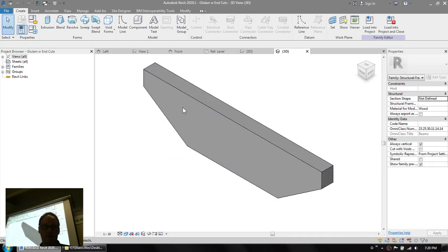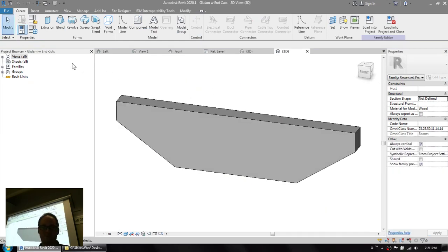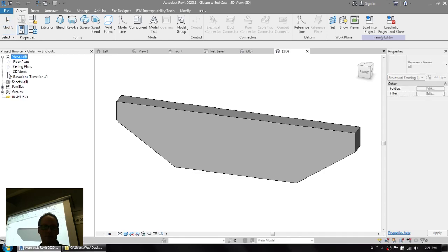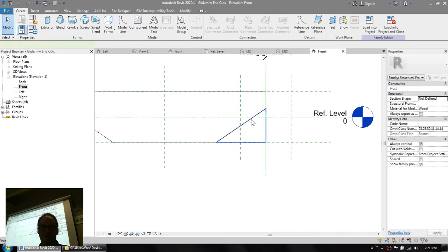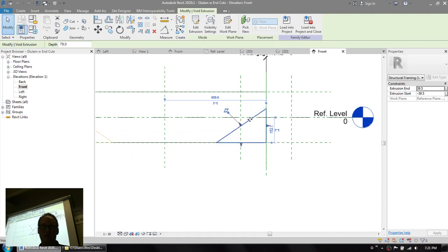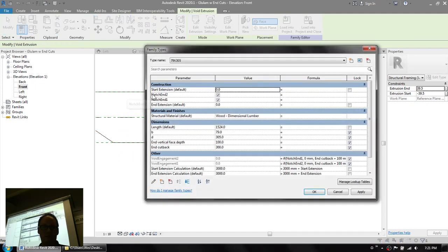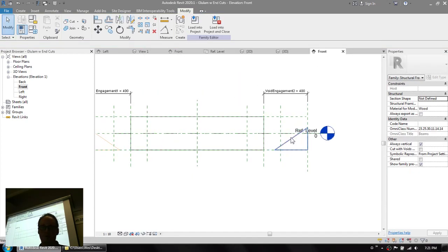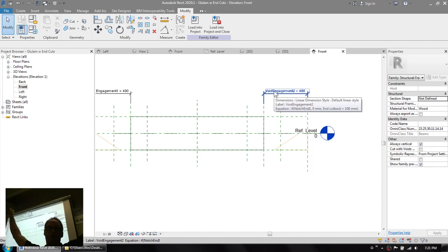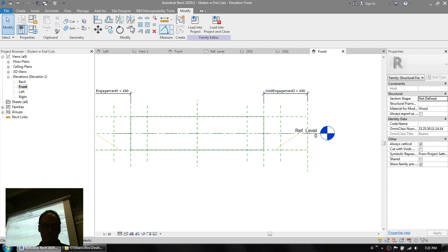In this folder for tonight, this is a structural beam family, and you folks can use this. We used it in our structure class when we were building that gazebo. So here it is. There's a little void in there, and when we don't want that void to be used, inside the family there are these boxes with check boxes. So if I don't want the voids to be notching these ends of the beam, and I hit OK, what happens is that inside this family, the voids are moved away with a length parameter, a dimension. The dimension simply grabs those voids and moves them far enough away that they're not going to cut the ends of the beam.